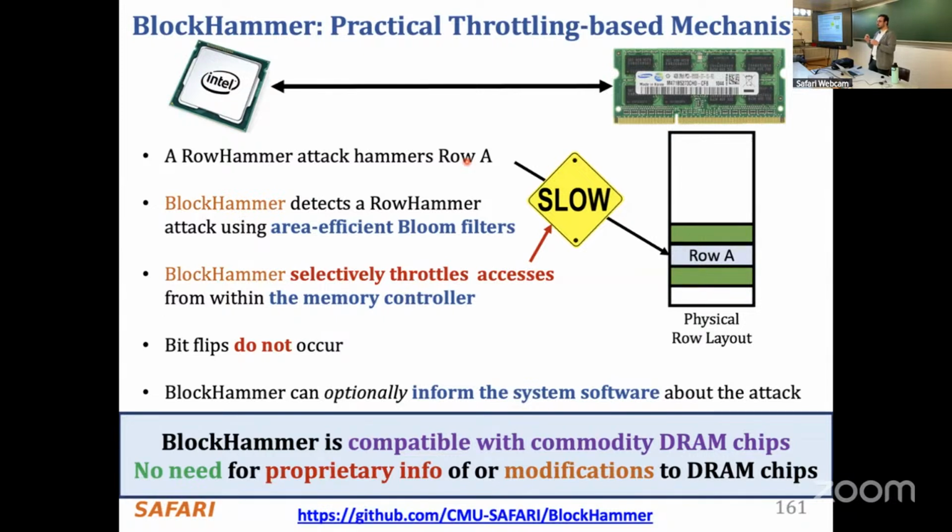So are you familiar with RowClone? You can open two rows at the same time in a DRAM bank, and they share their charges in their capacitors, and you can effectively copy one row to another location. So if you have a spare buffer row, for example, you can copy rows back and forth and change the layout. There was a paper, I'm blanking on the name, I forgot, from some Korean researchers doing exactly that. There's another paper that they did as a follow-up. They randomized the row address layout quite a lot.